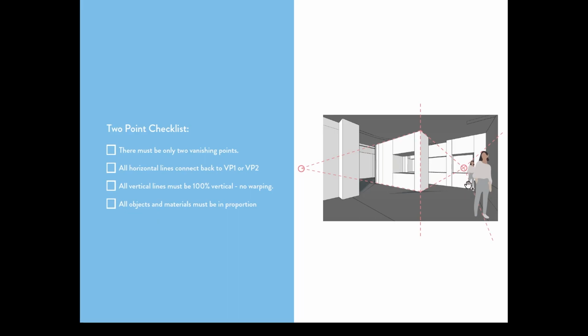So if a person is this tall back where she's standing up against the cabinetry, we project out through her feet, out over the top of the head, and that tells us how big they can be. So let's go into SketchUp now and have a look at how to correct our vertical lines to make sure they're looking good and to make sure that we're setting the camera to the right eye height so that we're all at the right proportion and scale.